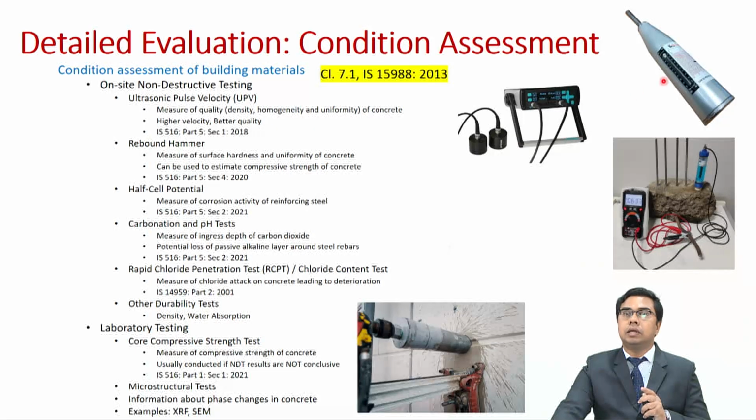But if both are giving conflicting values, or both are giving inferior values for concrete, then in order to be sure about the quality of concrete, we shall perform some laboratory tests. I just gave an example related to these two equipments which are most commonly used. However, this is true for all non-destructive testing.